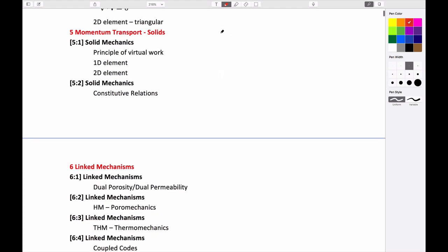And so the system of equations for solid mechanics, even though it was probably not written this way, would be something like applied forces as a vector would be equal to a stiffness matrix times a displacement, plus a damping term multiplied by a rate of change of displacement, plus a mass term multiplied by an acceleration, u double dot.